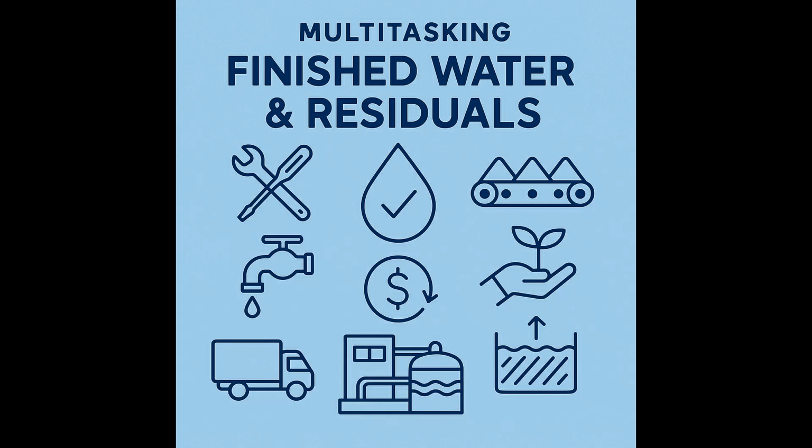Okay, let's get into the nitty-gritty of the machines themselves, the ones that actually squeeze the water out of the sludge. What are the main dewatering technologies we typically see in these medium-sized plants? Sure. The 3 workhorses you'll most often encounter are centrifuges, screw presses, and the older standby belt filter presses. Let's start with the centrifuge.